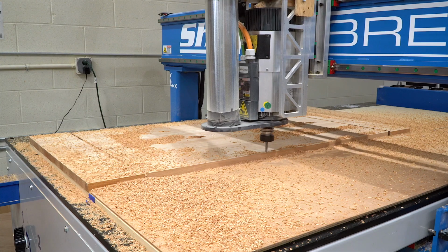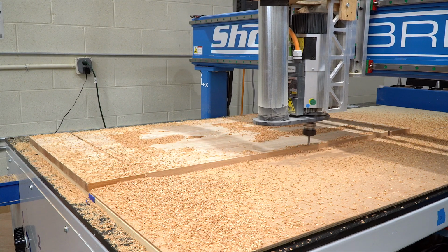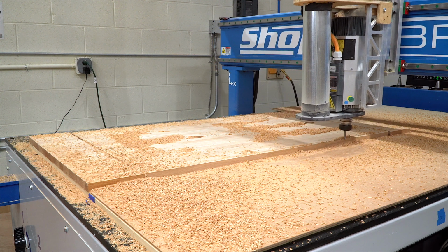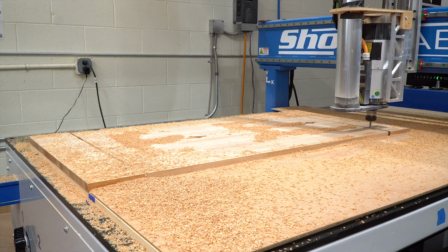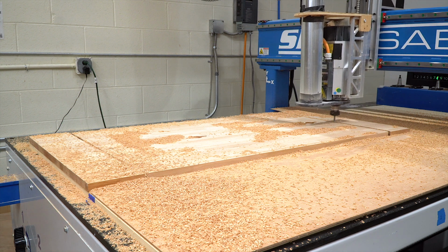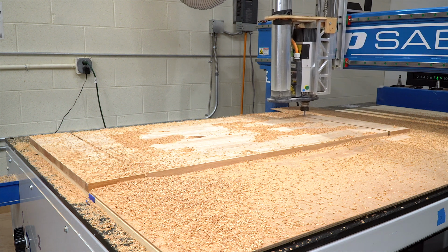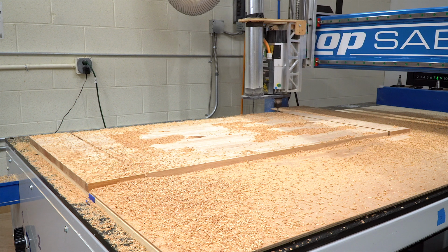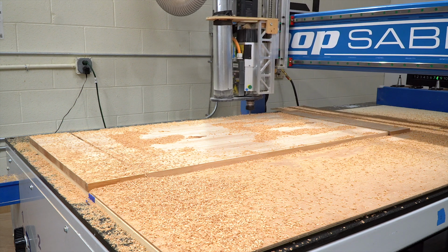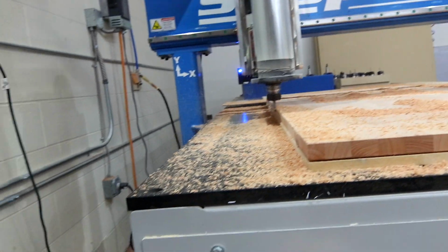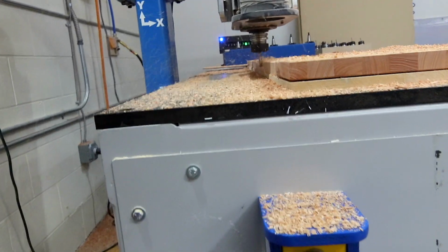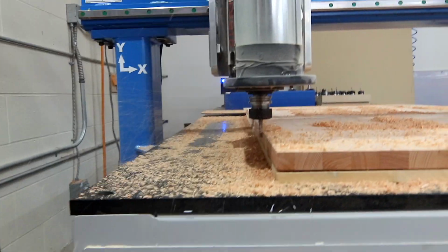So there's an annoying bug in Fusion. When you do a ramp, sometimes it will extend the ramp for an incredibly long time. So that's what this is doing right now. It's ramping at probably like a degree or 2 degrees when I really want it to do 35 degrees. To fix that, you can change the max step down amount to 0, which is just really strange, in the ramping or the last tab of the settings.